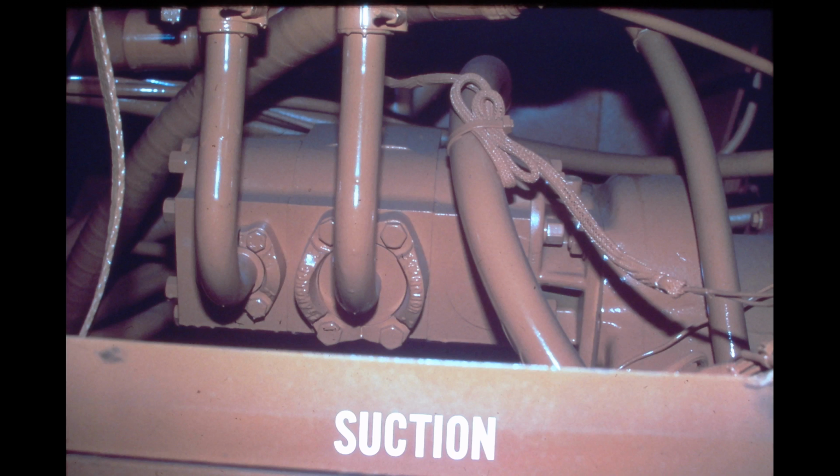The suction area of the system is the reservoir to the hydraulic pumps. A problem in this area would be aeration or cavitation, which would result in noise from the pump and erratic operation of the entire hydraulic system. The items to check would be the fluid level in the reservoir, the strainers, the suction lines to the steering switch pump, and to the loader pump.